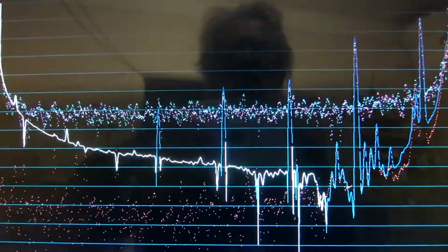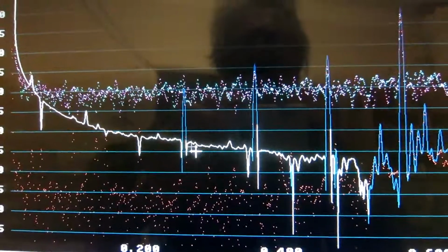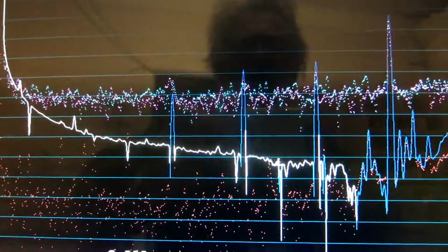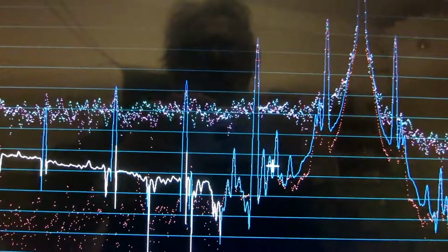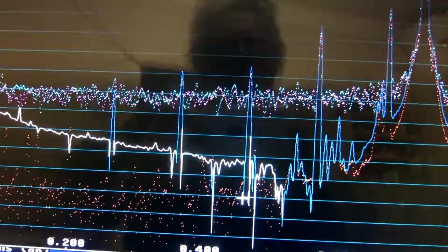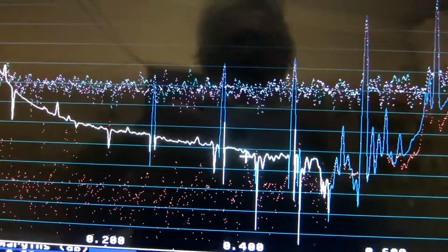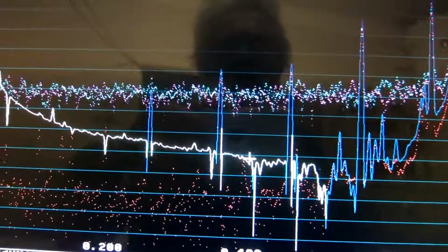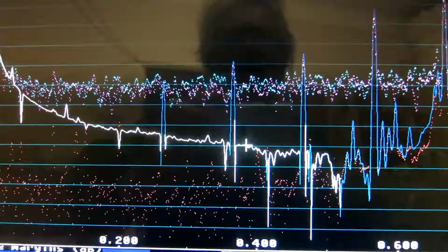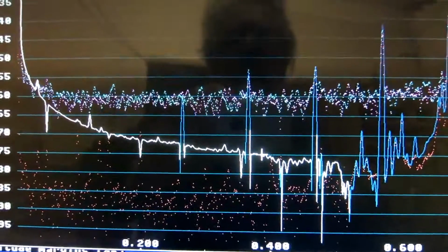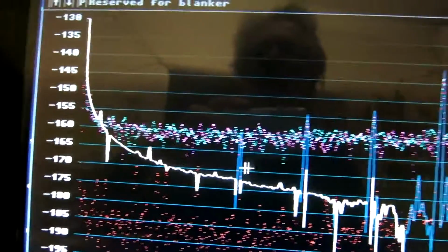And for AM noise, here, it looks a little bit odd that it bends here, but on the other hand, it seems unlikely that the negative signal from the center can contribute at this point. But there is some spur here, and maybe there is also here something, I don't know. Anyway, I have a better result now, and I will stay with this and investigate other aspects of this oscillator. But first I will take down all the numbers from this measurement.